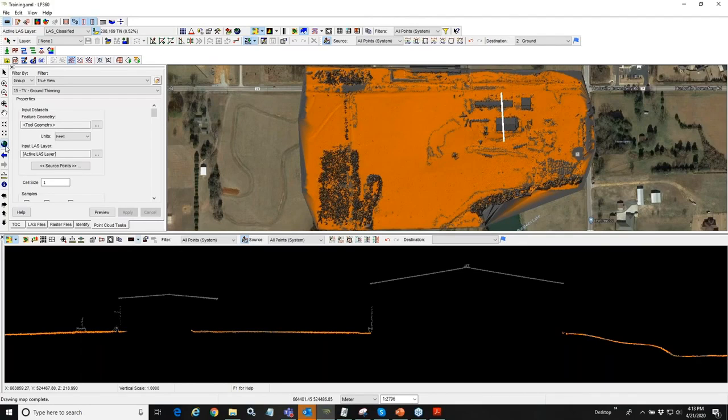There's an additional step that we want to do in the workflow with TrueView that's really important, especially when working with what I call the automotive class of LIDAR, TrueView 410 and other systems. If you've worked with data from these kinds of systems, you know that they can have a lot of shot noise. Lewis mentioned this. I think he referred to it as fuzzy. That's typically how I call it as well.